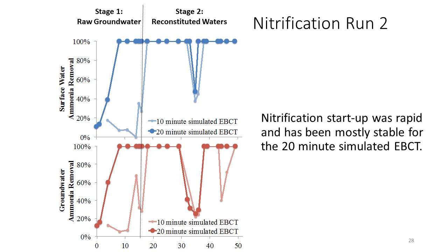Can you explain the simulated EBCT? This is Scott. As opposed to just EBCT, why is it simulated? The actual EBCT is close to about 3 minutes, but we wanted to make sure that our data is comparable. Often in the literature, if you see bench-scale studies, you'll see 8 minutes or 10-minute EBCTs, and at full scale, that's really, really huge.